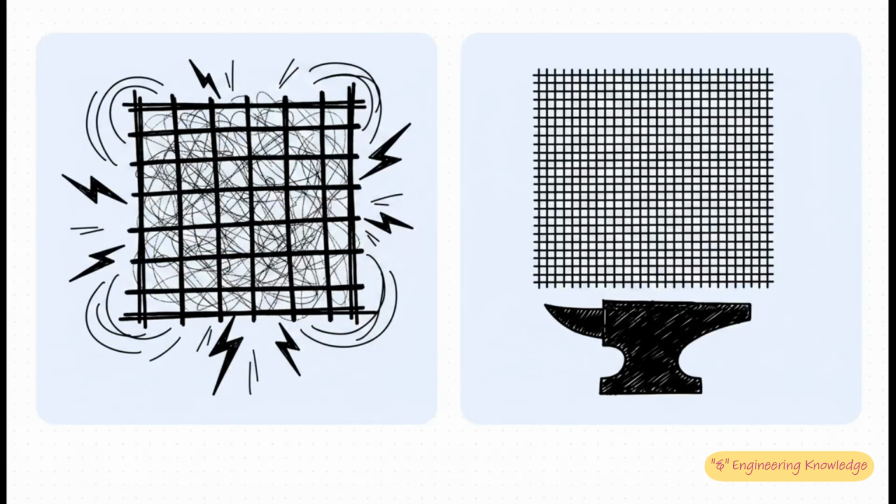Now, throughout this study, you are walking a real tightrope between two extremes. On one side, you have the coarse mesh. Yes, it's incredibly fast to compute, but it's full of massive, dangerous errors. On the other side, you have a uniformly fine mesh across the entire model. Now, while that might sound perfectly accurate, it's actually a trap. It will eat up an enormous, totally unnecessary amount of your computational time and memory.